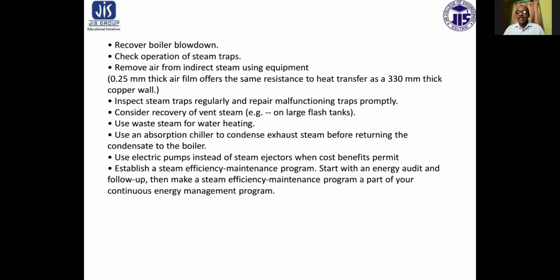So if air is trapped inside the steam lining, we must remove that. Generally this applies in the case of riser tubes in a boiler. Inspect steam traps regularly and repair malfunctioning traps promptly. Consider recovery of vent steam. Use waste steam for water heating.